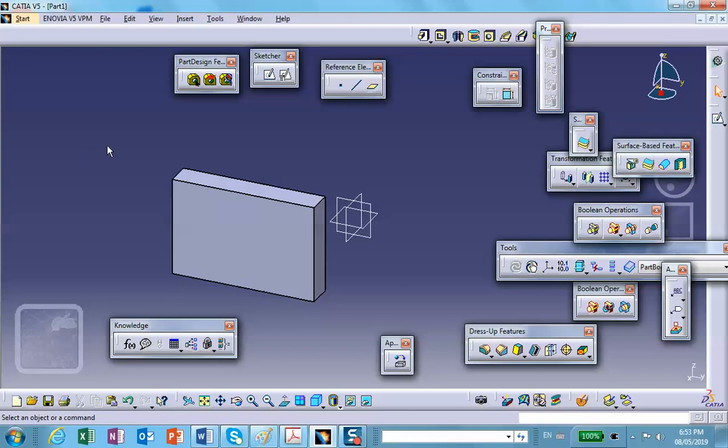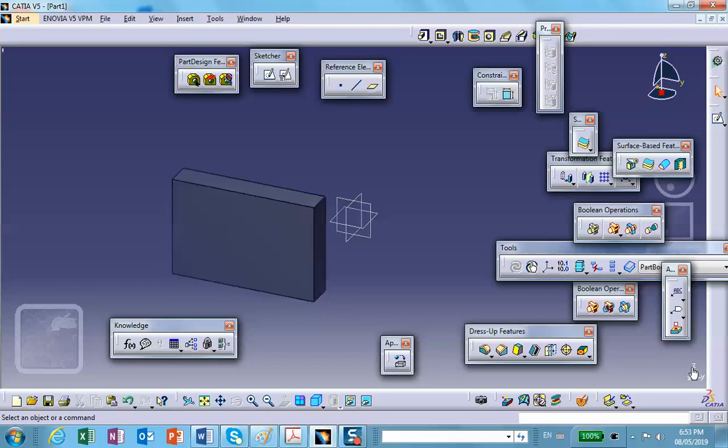But what you should do is go and click on this coordinate system. That means the tree is going to get selected. See that? The tree is selected, right? Because the box, the object that you created, is dim. Now you can go and say fit it. So the tree has been selected and you say fit all. There.